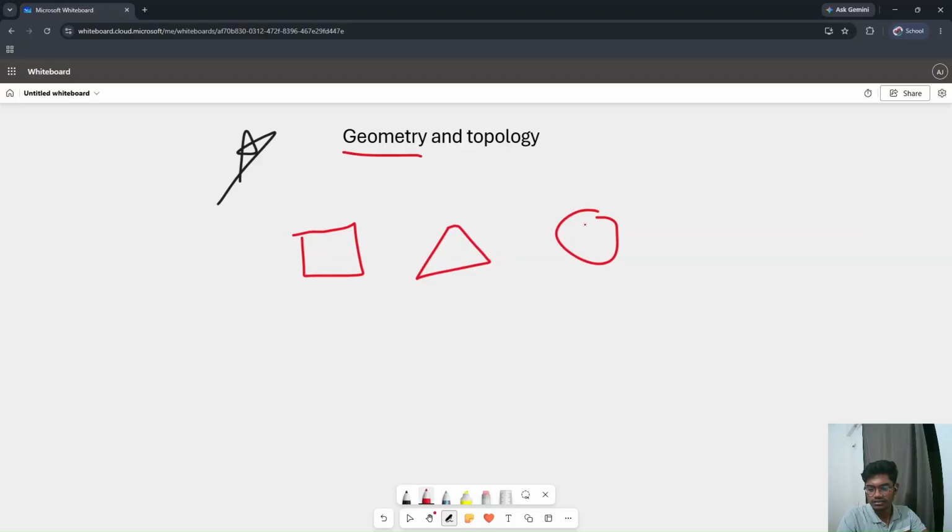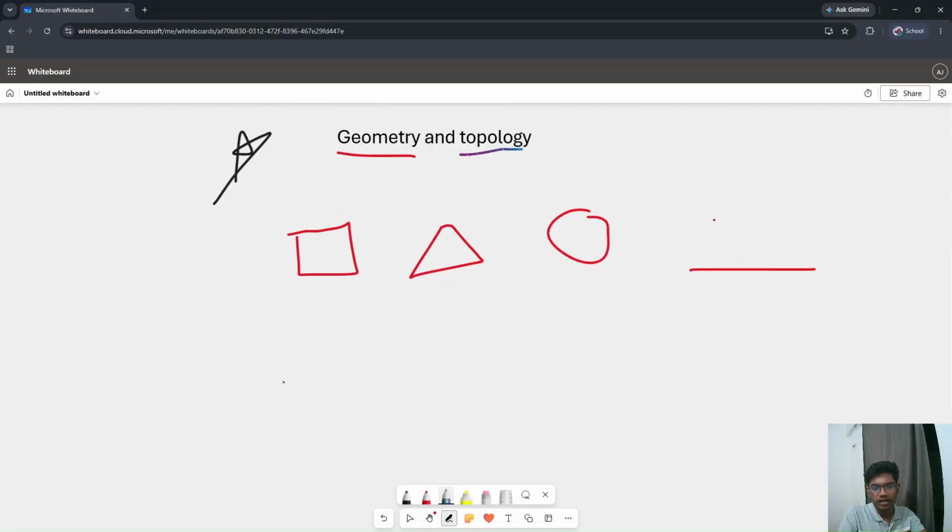These are your points and your lines, and all this is considered geometry. Now, topology means how all this geometry joins together. We talked about the cube: multiple faces, the squares, joined together and create a closed shape, a solid cube, right? So it defines the connections between all these geometries.